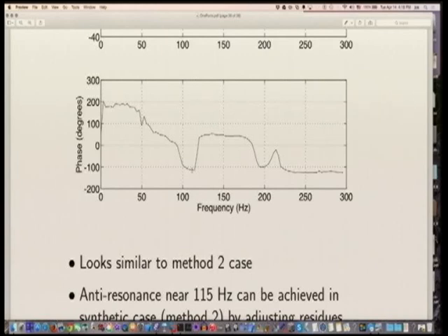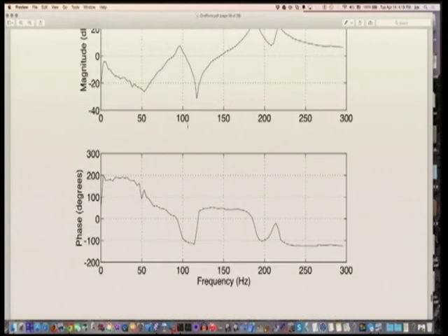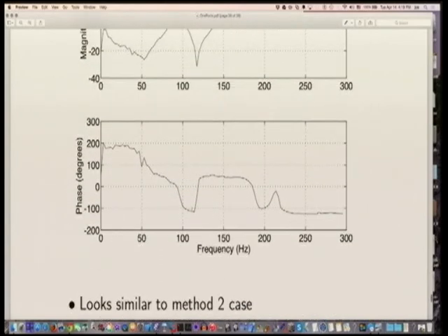It's like a big Helmholtz resonator, where the guitar body is the big spring of air, and the air in the sound hole is a big mass of air, and so that's your mass spring oscillator, Helmholtz resonator. And so above that, it looks like a, what does it look like, a spring or a mass? So we just crossed a mass. If we're looking at admittance, yeah, we are looking at admittance, and the mass is 1 over ms. So we'll be looking at minus 90 degrees. Good. So it's looking like a mass above the Helmholtz resonance.